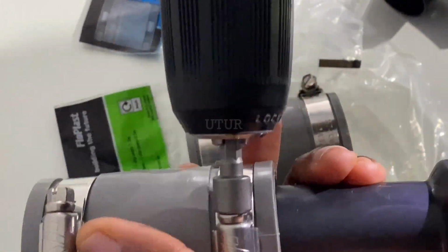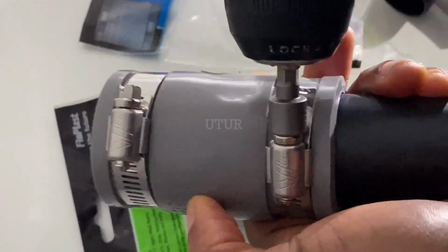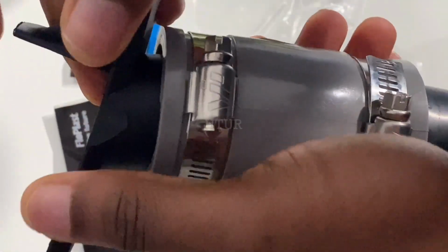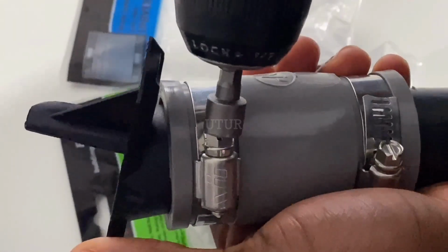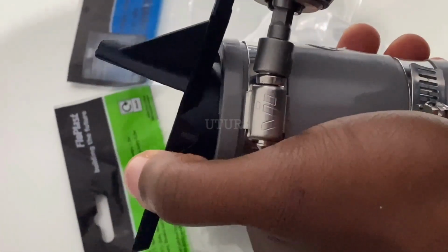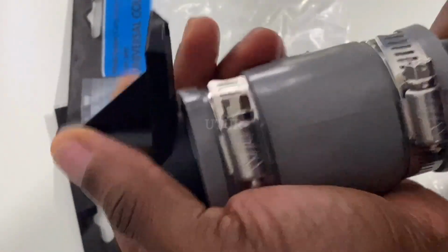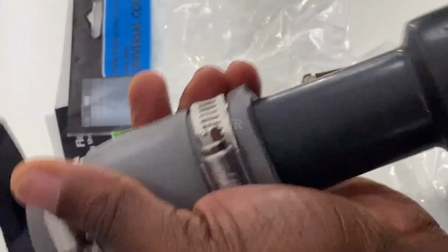And so we torque tighten it clockwise a little bit more to close that gap, so that we've got a firm connection and there is no debris escaping when we're extracting the wood dust. And on visual inspection on the inside of the coupling, there isn't any gap between the coupling and the non-flexible hose. So I will install the vacuum adapter on the other end, torque tighten it to make sure that I've also got a firm connection on the other side.